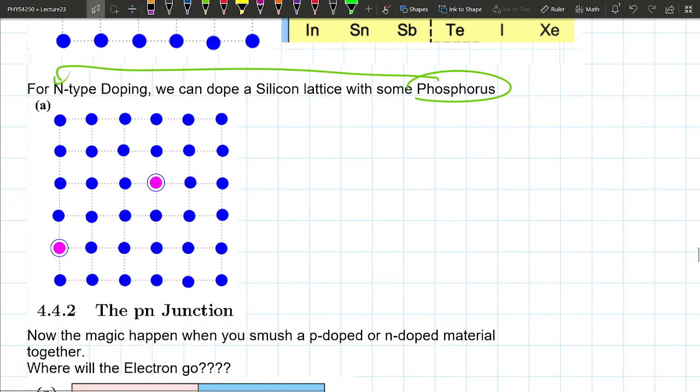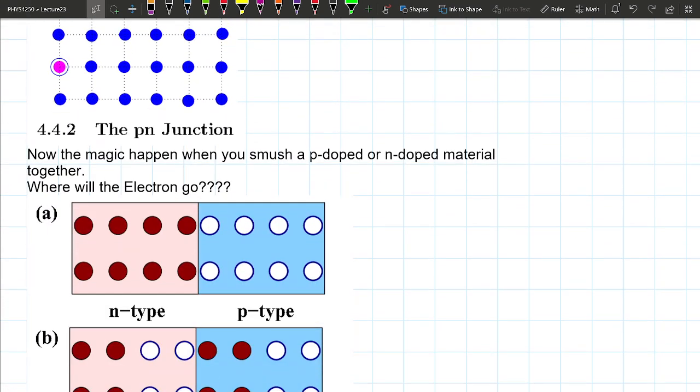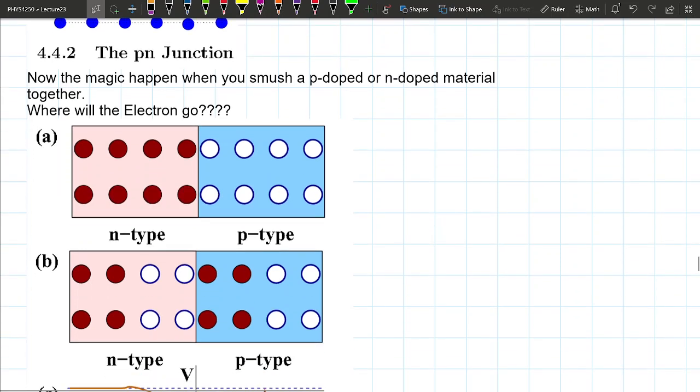So what the video just showed you is that when you sandwich these two types of materials together, one of them has extra electrons that it wants to get rid of in a probabilistic sense. The other one has extra holes for these electrons to fill. So when you put them next to each other, some of the electrons from the N-type material will migrate over, in like a microsecond. That's pretty quick, because you're just traveling like 2 nuclei over.